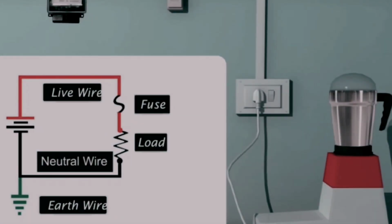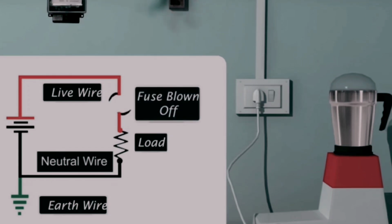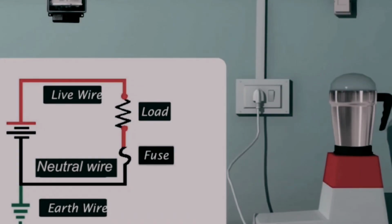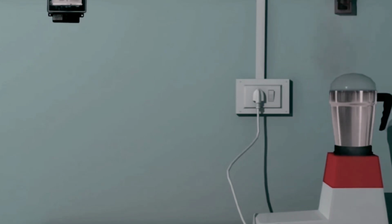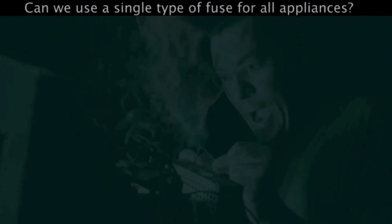The fuse is always connected to the live wire. When the fuse blows off, the entire circuit becomes neutral. If the fuse is connected in the neutral, the circuit remains live even after the fuse melts. This cannot prevent damage to our electrical gadgets, which will still be live. Can we use a single type of fuse for all connections of various current strengths? No. Each fuse has a specific current rating.